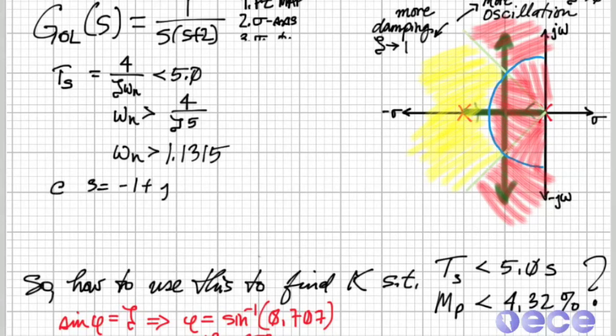So now we can check to see whether a specific value is going to work. If we look at the particular plot, in this area right here, it's really close. So we can't tell whether the root locus actually passes through the points that allow us to have a good controller. We want our controller to have these capabilities, but our controller is limited to only be on the root locus. And if the root locus passes inside that blue half circle and goes through the lines defined by zeta before it gets out of the blue circle, then we'll be unhappy.